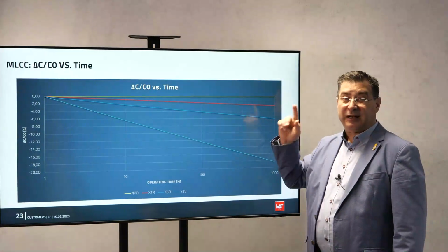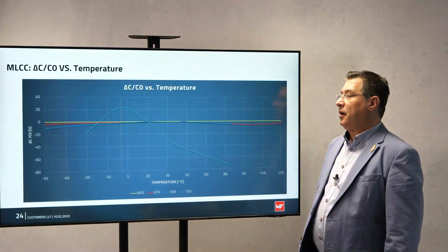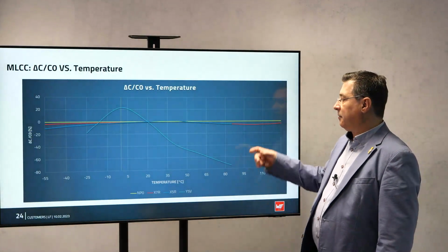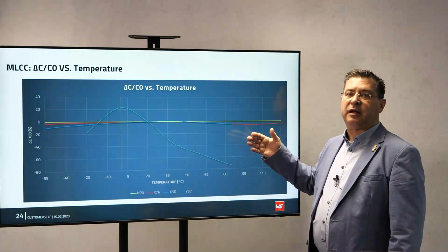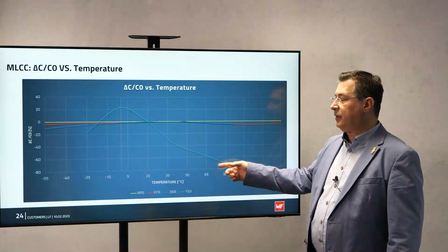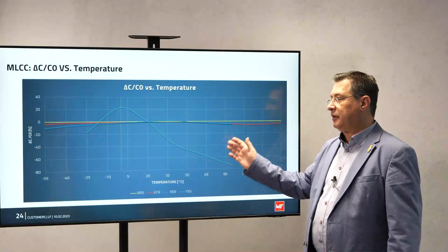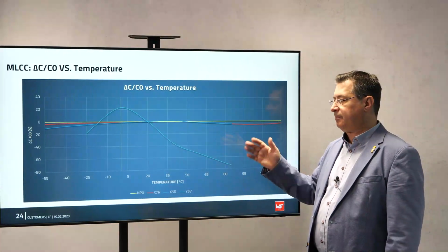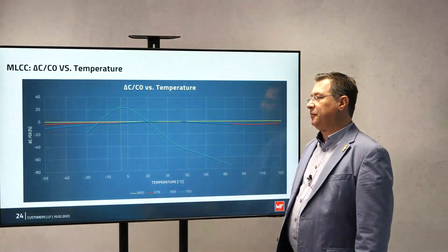Please consider that ceramic multi-layer capacitor, not tantalum, ceramic. Drifting in temperature is not a big deal. NP0, X7R, or X5R doesn't affect so much, but Y5V, this is the reason why we don't have them and it makes no sense to use them, because they have temperature drift, they are not stable. You pay just to have something nice on the PCB.